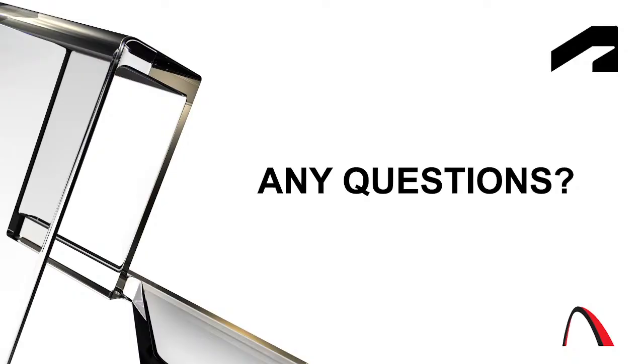On the sides, the spring elements will be connected to the beam, and then in the middle where you have the slab, the spring elements will be connected to the slab. That will be the difference, because at the moment we have the slab all around, and then we have the spring elements throughout the slab. But if you put in an edge beam on the sides, then the spring elements will be connected to the beams, and then you will have other ones inside where they will connect with the slab. But just make sure that there is a connection between the outside beams and the slab as well.